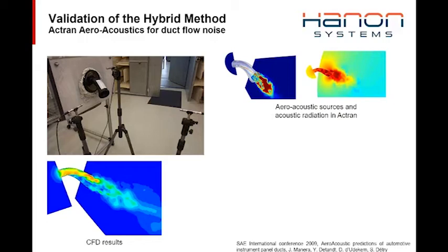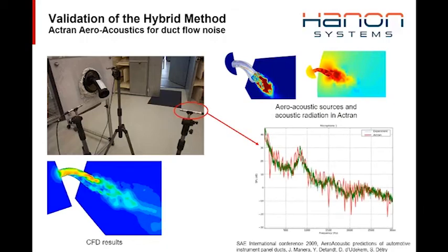Yeah. Basically, as we explained before, there are 3 steps we do when we do the CFD for aeroacoustics. The first step we do is typically establish the flow using a steady state simulation, and we use this as a base for everything we do later on.